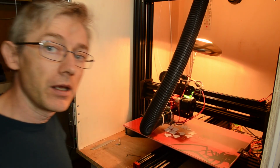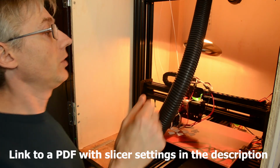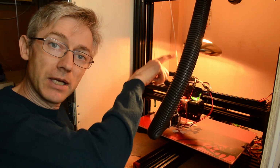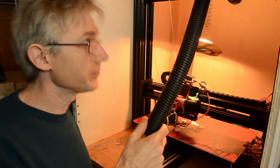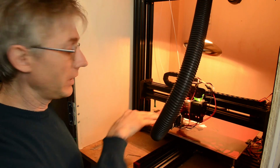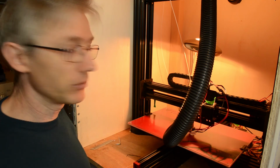The hot end, it's 250 degrees. To avoid having the filament melt too early, I put this vacuum cleaner hose transporting room temperature air directly to the fan of the hot end. So this will take a couple of hours. When it's finished, we have a look at the result.